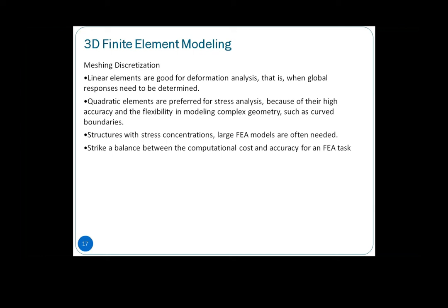One of it is that your discretization, your approximation, is good. So the element size that you use is good. Like what I mentioned to you, using a larger mesh size compared to a smaller mesh size, if it changes a lot, that means your result is not reliable yet. So you have to go through that independence test.